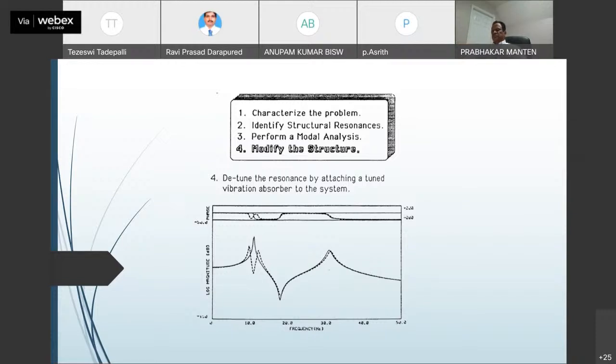When this first system goes into the resonance it's tuned to, the second system picks up all of that and goes into its own state of resonance. So a single degree of freedom system essentially becomes a 2 degree of freedom system at that point of interest, and essentially you have avoided that resonance. These are commonly used all the time in well defined systems, like machinery, where rotating speeds give very fixed fundamental frequencies, a very clear, well defined band, so that you move away.